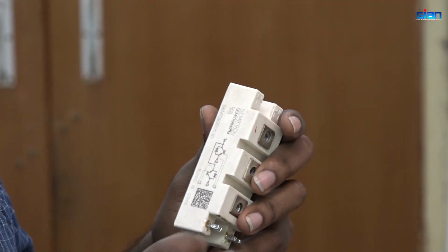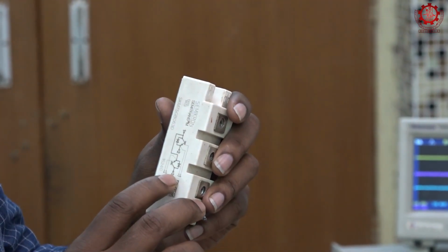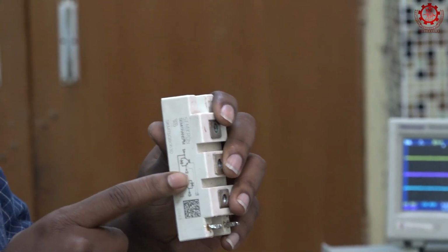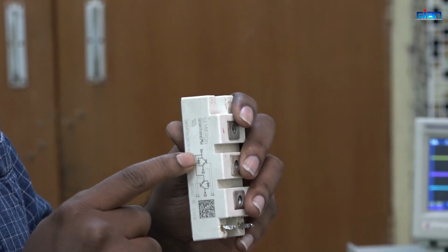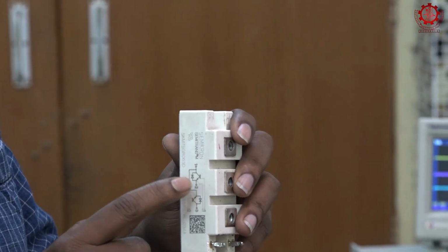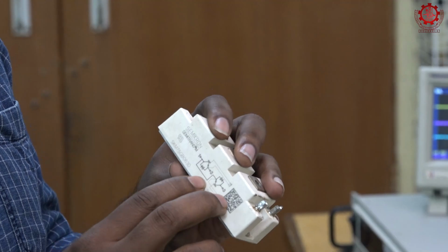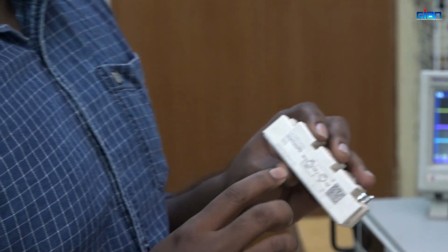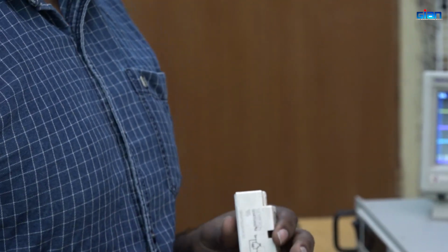Three terminals are the connector of the upper switch, one is a common terminal for the upper switch emitter and bottom switch collector, and two terminals are the emitter terminal of the IGBT module. It works up to 600 volts and 75 amps. So I used this IGBT module to develop my bridges.